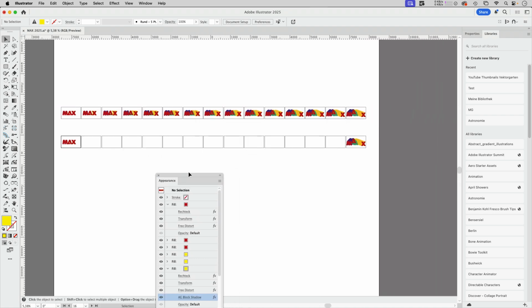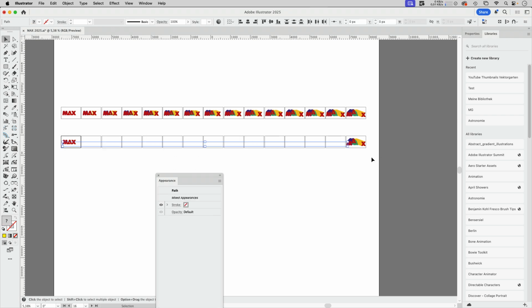And when you have effects that have different settings in the start frame and in the end frame, then you can create an animation. And in this case, Illustrator has a nice functionality to build an animation. So for that, you can select them both. And you see there are a lot of empty artboards in between. And I'm using artboards actually for exporting the animation I'm creating. I'm using GIF Studio for that, but of course you could just export the artboards as static images and piece them together in Photoshop. I have a video about that I'm going to link in the comments.